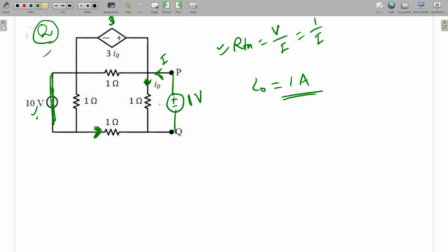So I am going to write the KVL here. So see, this is plus 1, and here this point I am taking as a ground. So at this point 1 voltage, at this point how much voltage will be? Minus 2. Okay. So what is the current in this one? Current in this will be minus 2 ampere. Okay. This will be minus 2 ampere. Here how much is the current? 1 ampere, so that 1 ampere. Minus 2 ampere, this direction will be. So what will the current direction be?